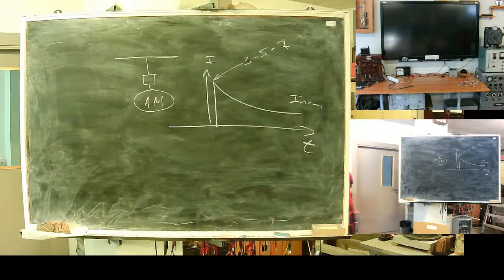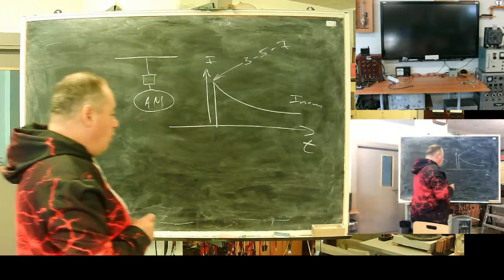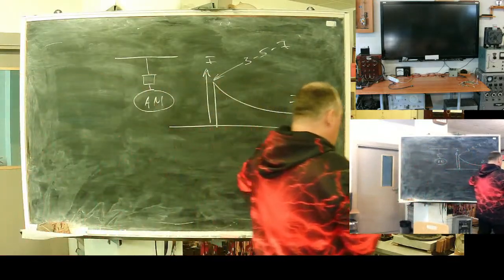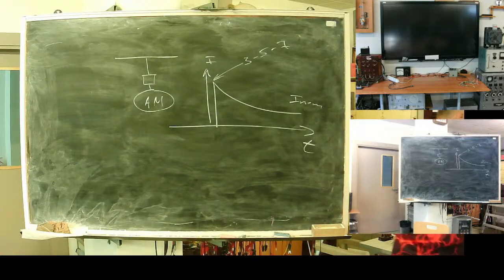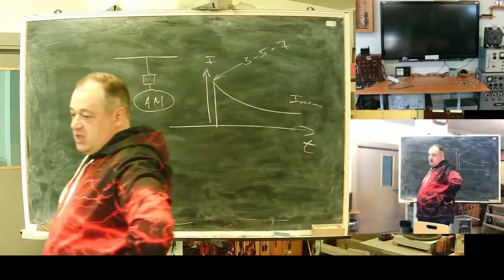It is possible it cannot start, something is stuck. Or one way to damage this machine is to attempt to start it with voltage lower than rated. So it will not produce rated torque and will not start.